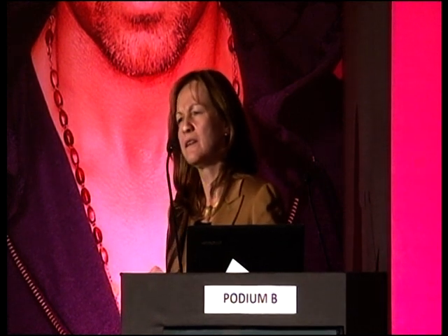We haven't done any. You're talking about cavity closures, I guess? What I'm talking about is the flashings. There's a lot of leakage which you find along with these windows, which come along in the construction, the way the construction is done in India. A lot of flashing details are kind of missing when it comes to using these products, which is a downside we find here.